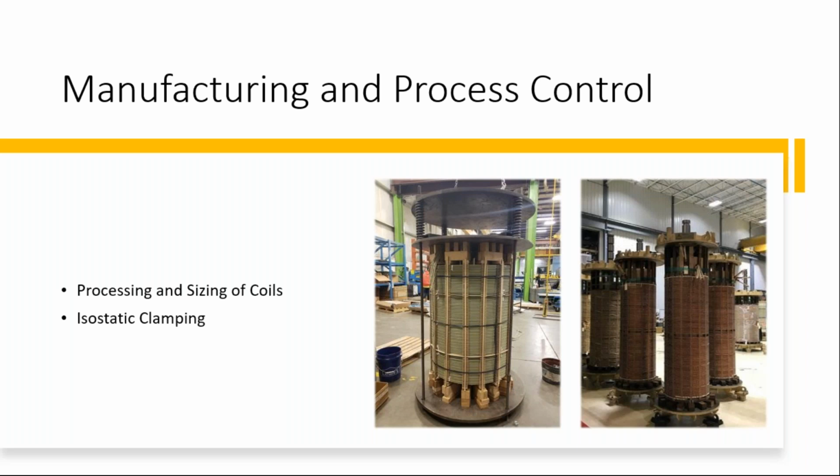So these are a few things, and another thing which can improve the behavior of this clamping process is if we use isostatic presses, which actually keep constant pressure on the coil as it is being dried, and another way, which is less expensive than isostatic, is using spring loads. So these are requirements from some customers, but it is not much known in industry. We could use a simple baking process and clamp the coils to the required pressure.